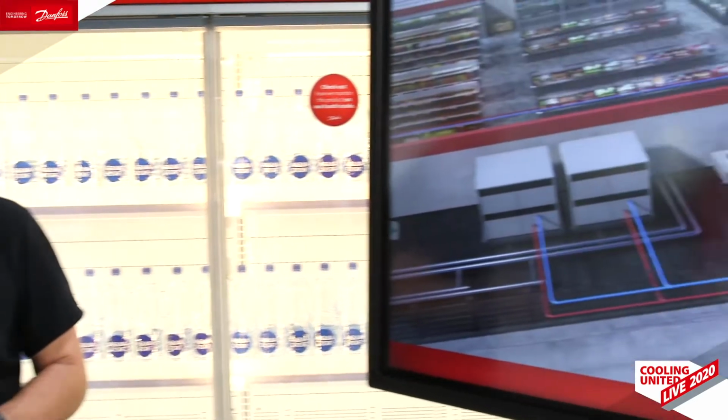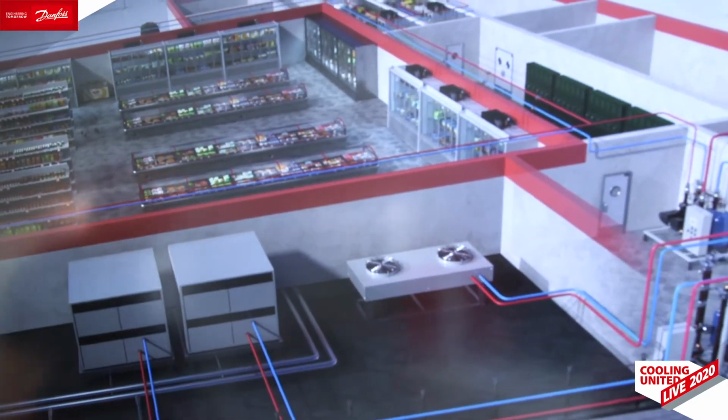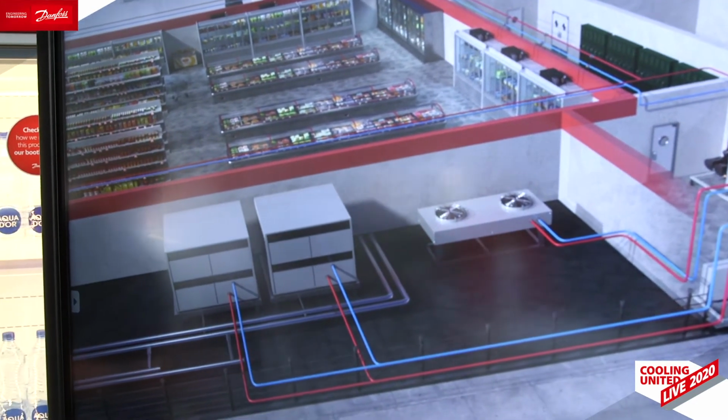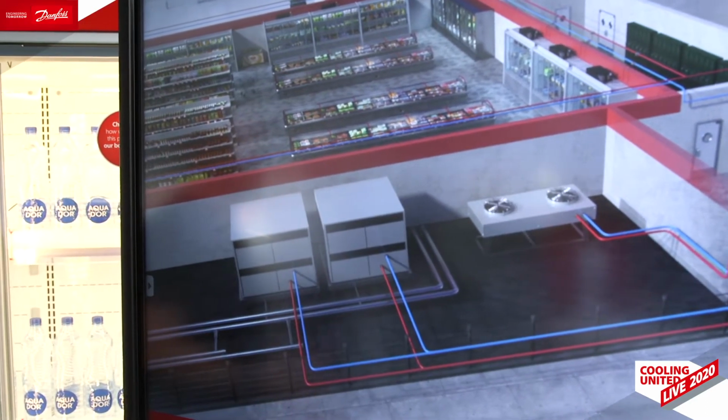My colleague Hans-Ole Mathisen will later on go deeper into that, but let's talk a little bit about that. It's important to remove the heat which is produced by the compressor up in the box on top of the cabinet, inside this box. And this compressor has a maximum allowed condensing temperature of approximately 55 degrees C. And to achieve that, you would need around 47 degrees C water supply temperature, which will be possible in most places in Europe by using a dry cooler only.